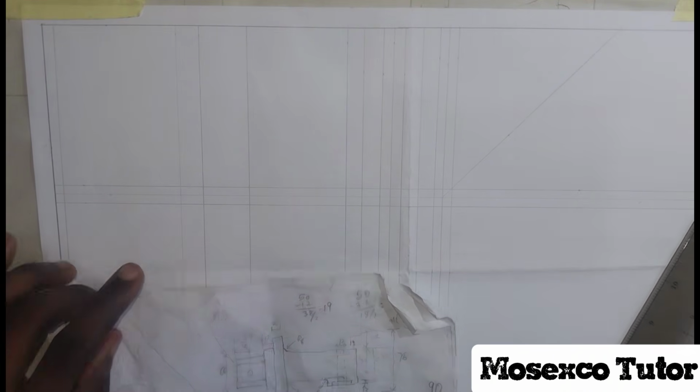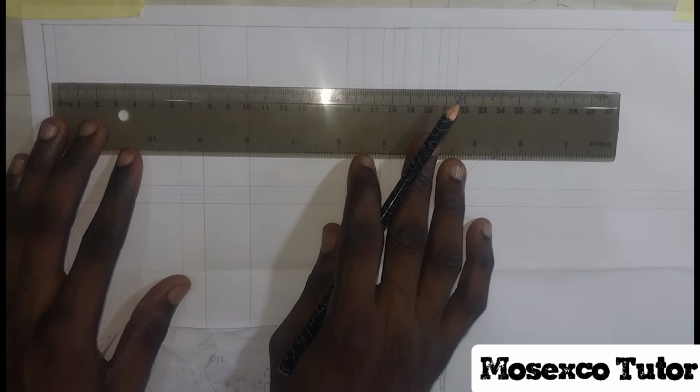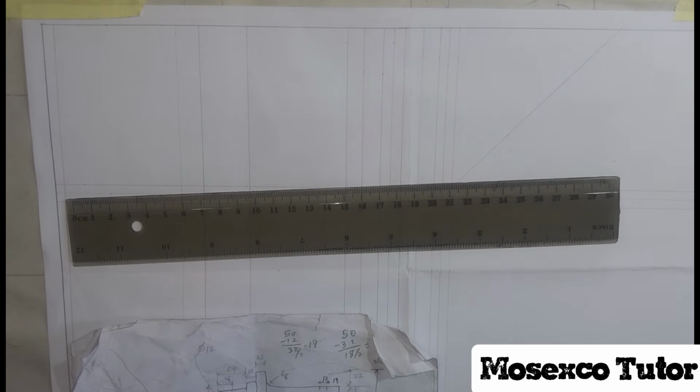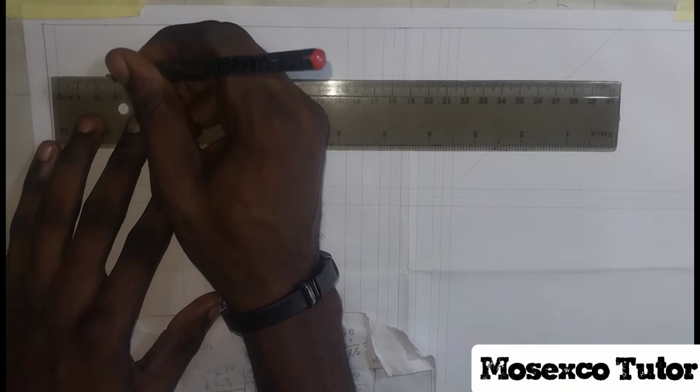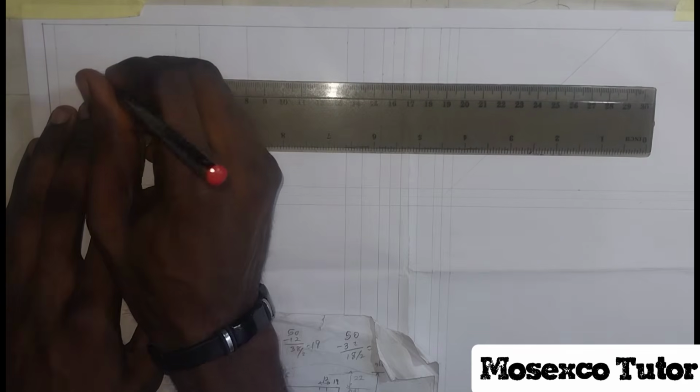Now I proceeded to the left hand side. The middle of that hollow part there is 2.6. After the 2.6, the circle itself is of diameter 1.2, that means of radius 0.6. So I firstly mark 2.6 centimeters, then from that 2.6 centimeters, I mark 0.6 left and right. I mark 2.6 from down, from the line where I got my 20.5, that last line, not the borderline. So 2.6, 0.6 left and right. I joined together as a straight vertical line.